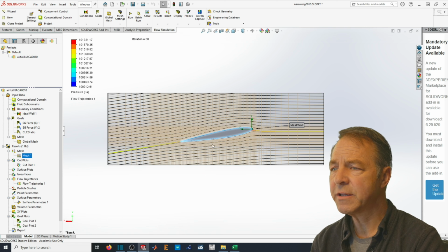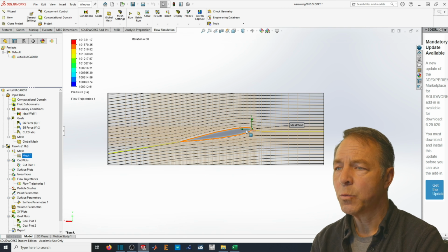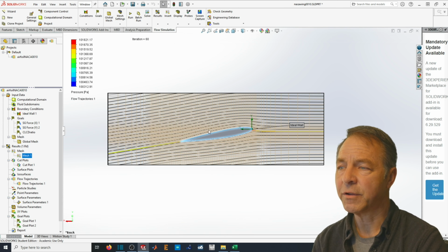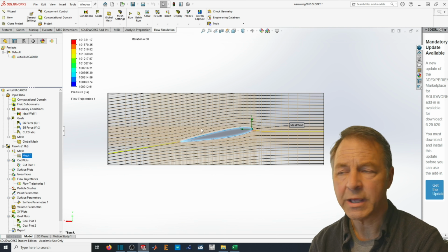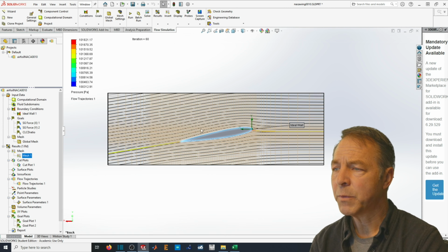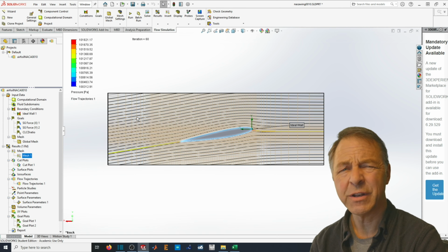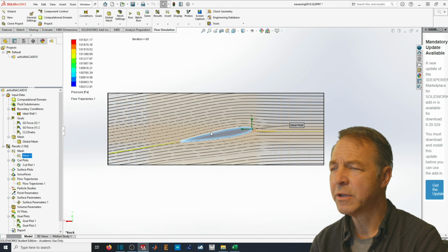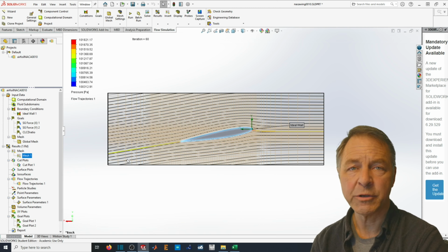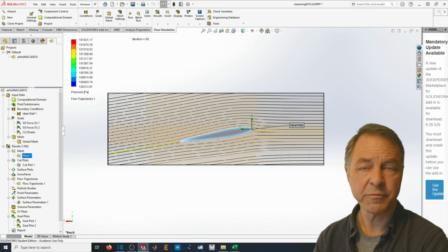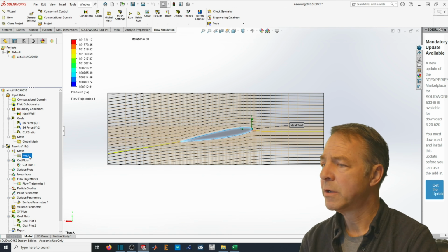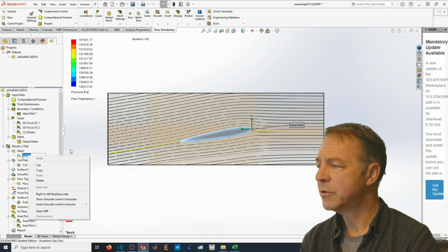So by increasing the grid point size, we may solve some of the detail flow close to the boundary layer, but we don't do it in a very intelligent way, because we're distributing an awful lot of points that are kind of unnecessary out in this region, and we're still not getting a terribly great inflation of the number of points close to the surface. So one of the things we can do to improve this